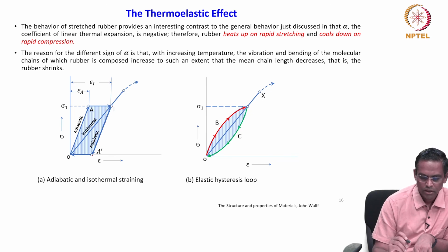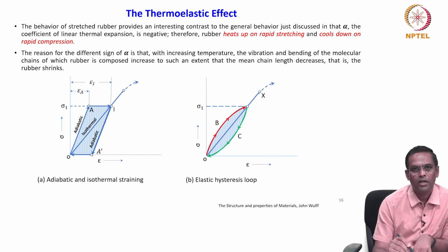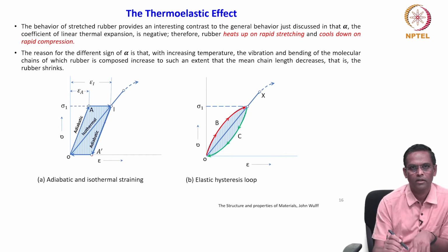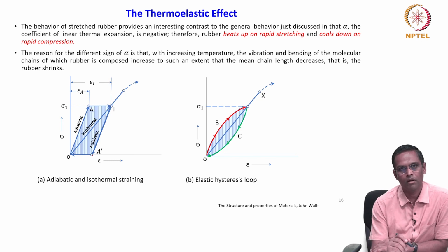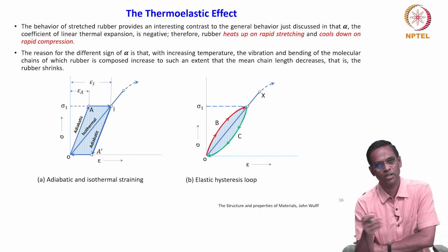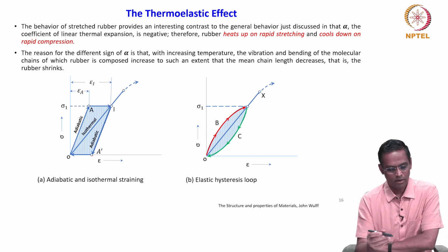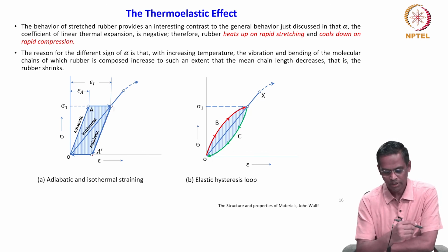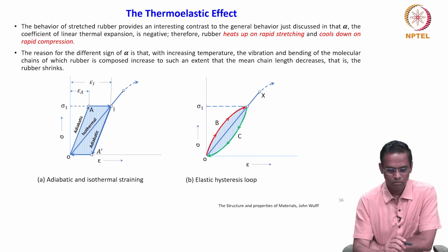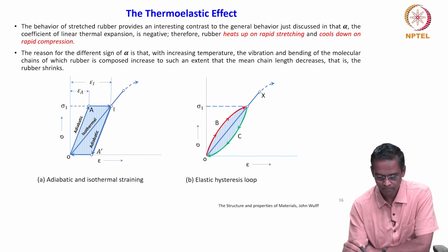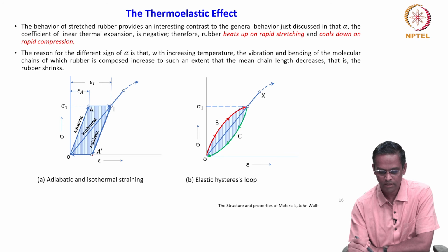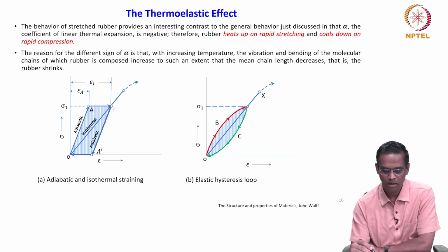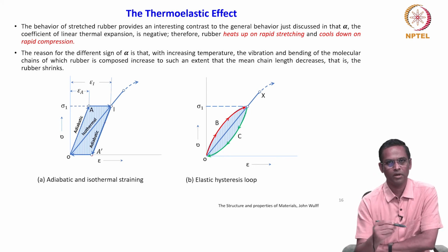Okay. So, this kind of cyclic loading or cyclic event like stretching, unstretching or stretching, relaxation involves some energy dissipation. That is the energy shown here. It is called hysteresis, the elastic hysteresis loop. The hashed region here is the amount of energy involved in this process.